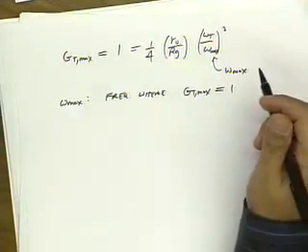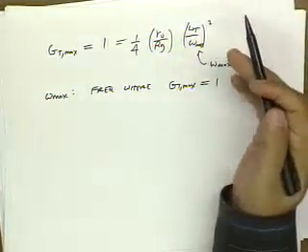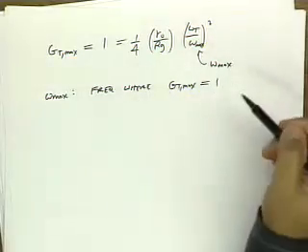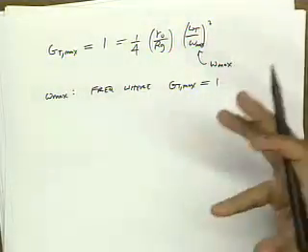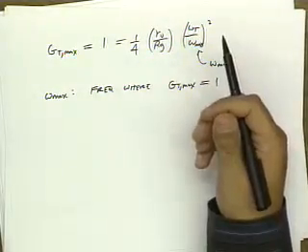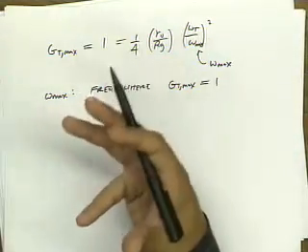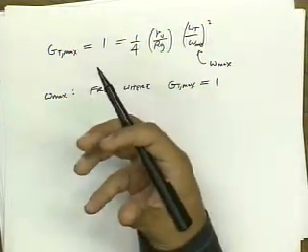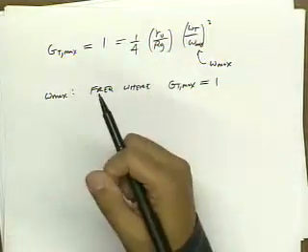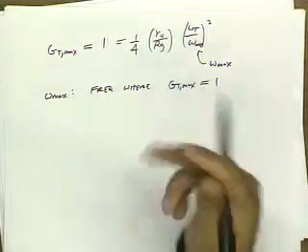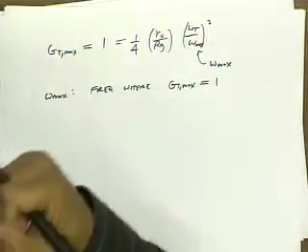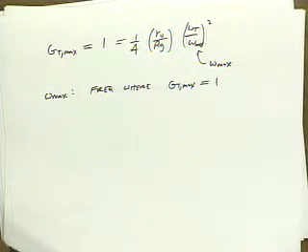And that in some way is a very nice metric. It tells me that if I go beyond this frequency, I can't get power gain from my device. In other words, the whole point of a two-port is to provide power gain. And if you can't get power gain out of your device, it's no longer acting like an active device. It's acting more like a passive device. And so this is a very important frequency.